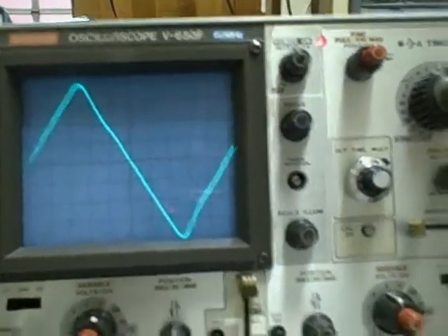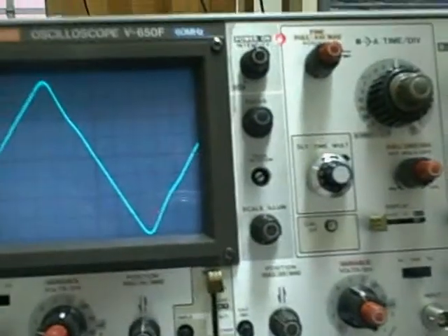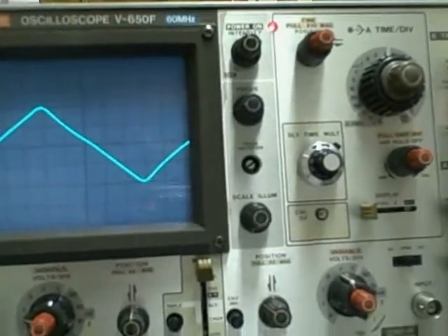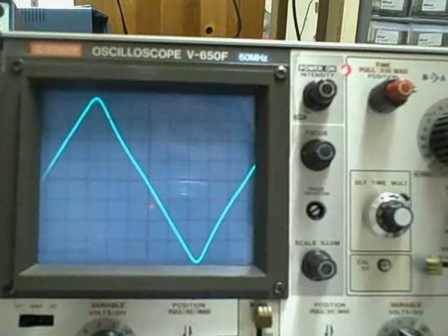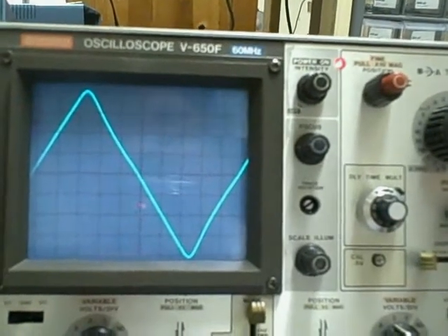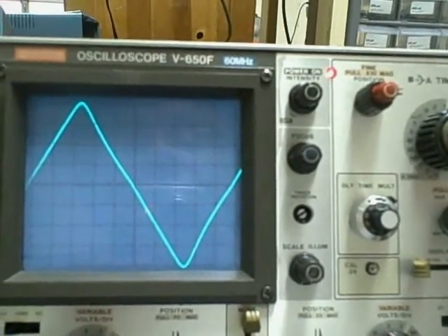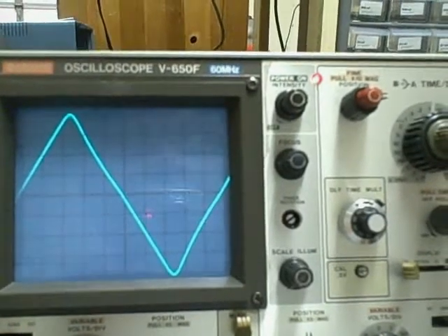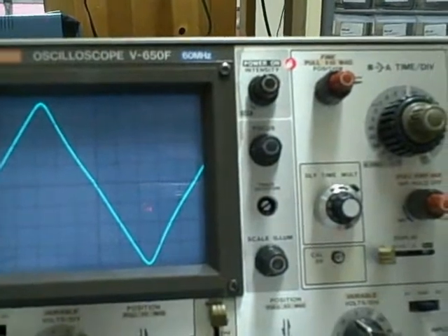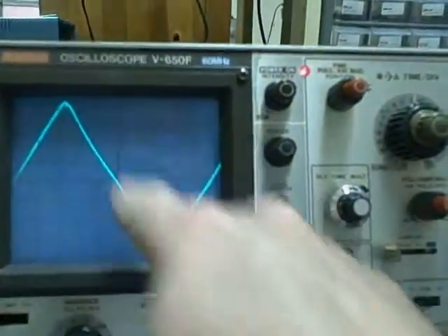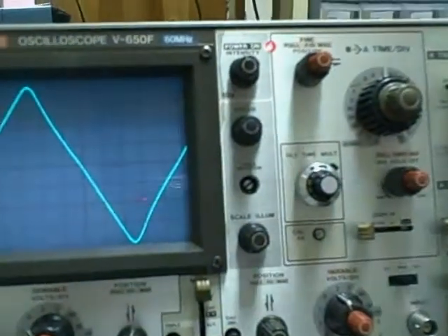Alright, let's drop our voltage once more. Up 4, down 4 divisions at a half volt per division. That would be up 2 volts, down 2 volts, 4 volts peak to peak, and again we are showing the 2 megahertz trace, 1 cycle in 10 divisions, so 50 nanoseconds.